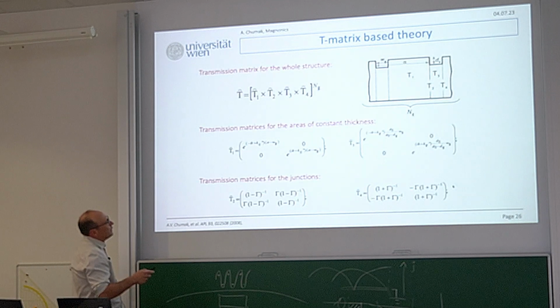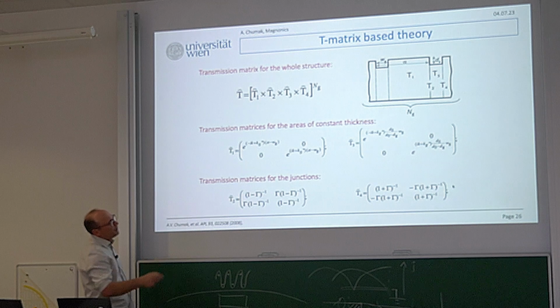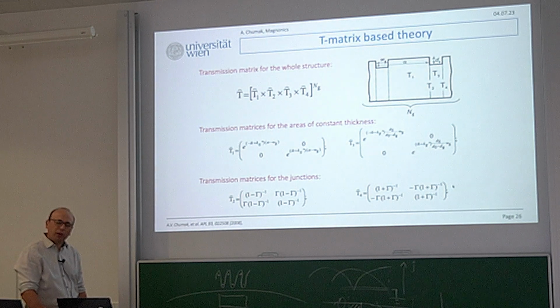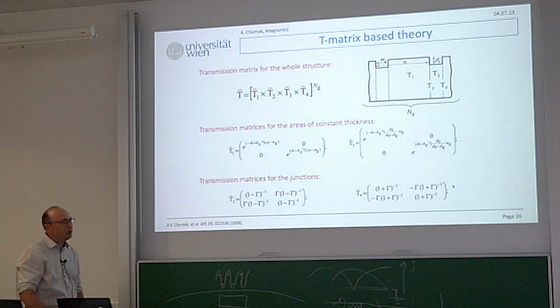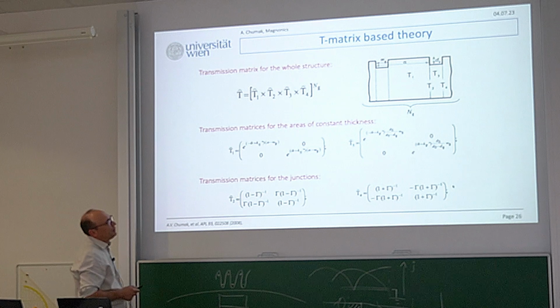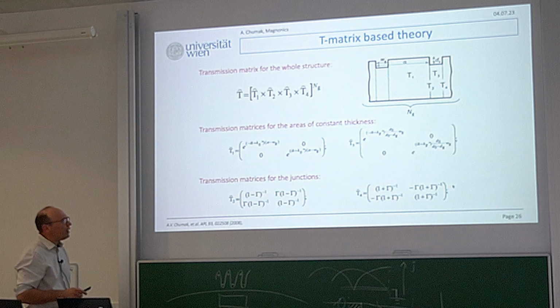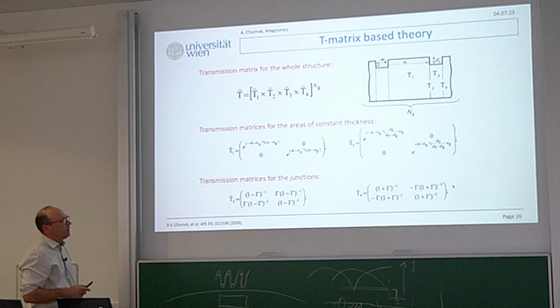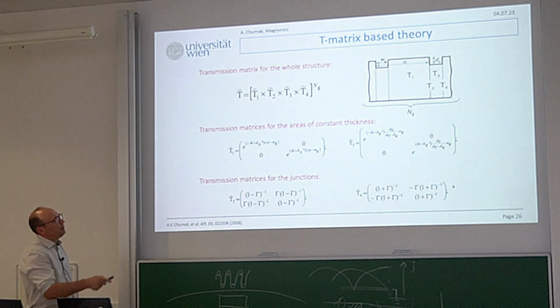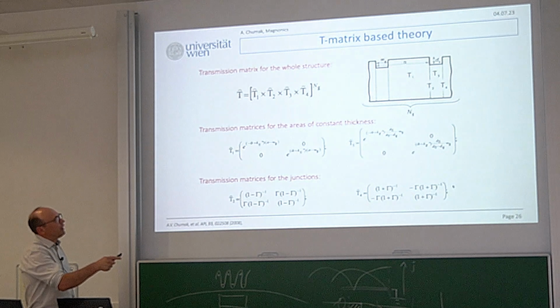So after you define this reflection from this region, then we are again coming back to microwave technique. There was this T parameter. So there are S parameters which we use every day in the measurements, but there are T parameters which are defined slightly differently, but the idea is the same. And why is it important? Because you can then define 4 T parameters for this reflection.